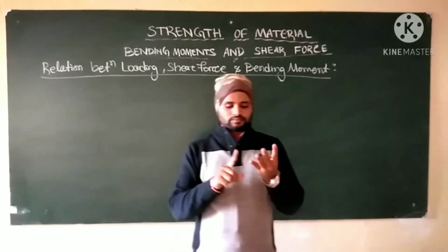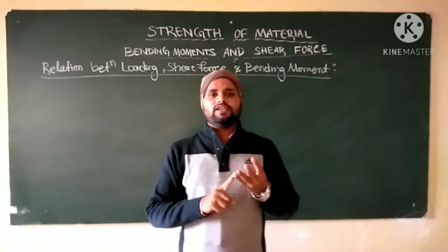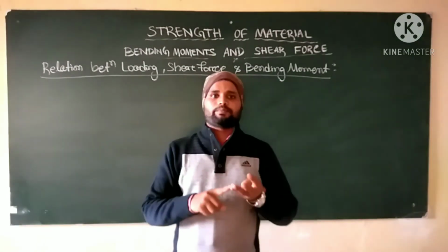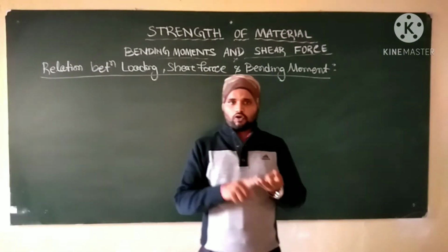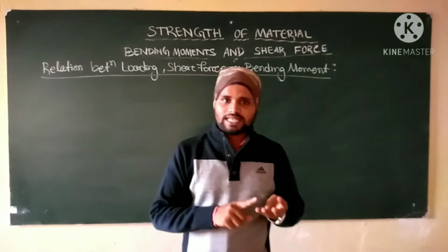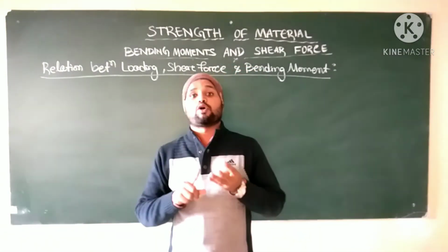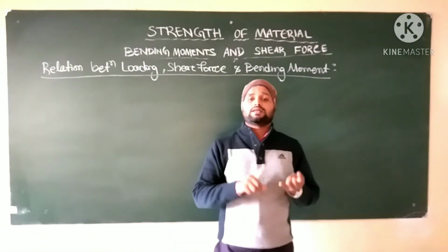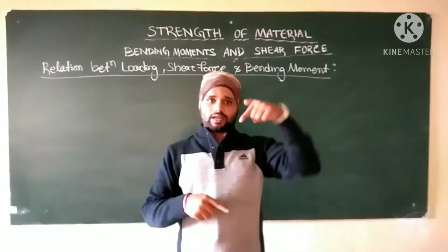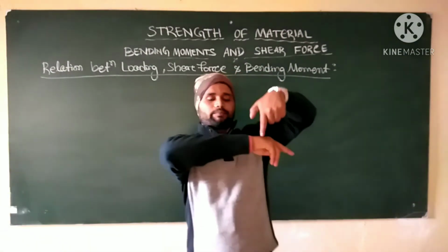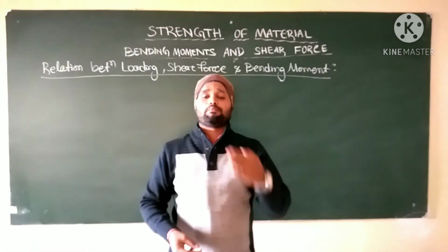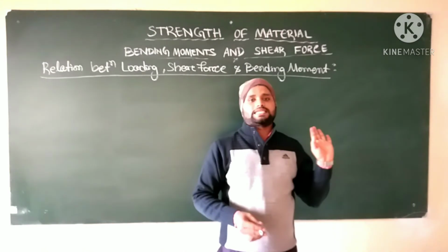What are those? The first one is, if there is a point load at a section on the beam, then the shear force changes suddenly. That is, the shear force line is vertical, but the bending moment line remains the same. That means whenever a point load is applied on a beam, the shear force changes vertically, but the bending moment does not change.